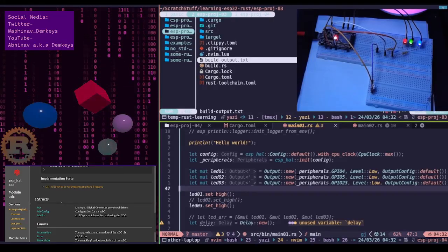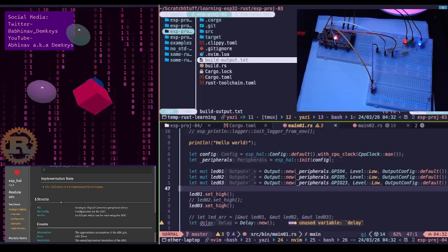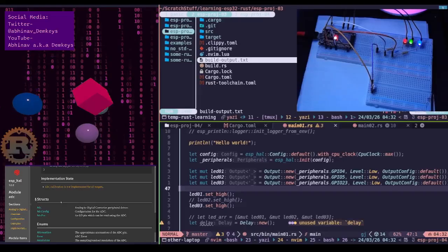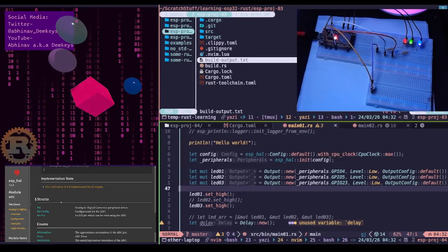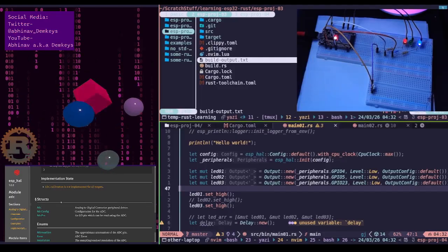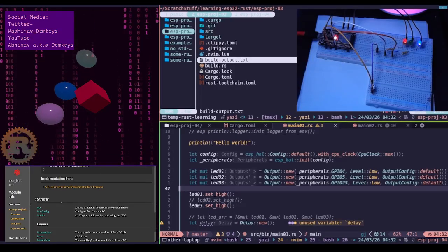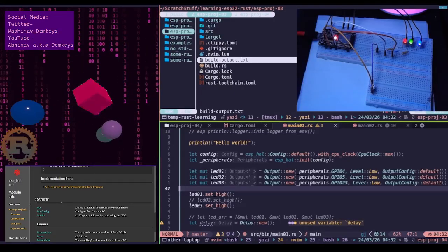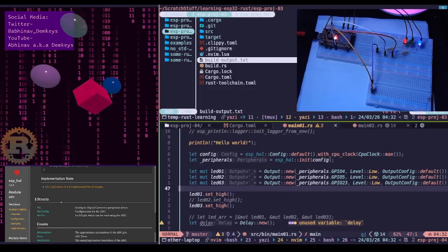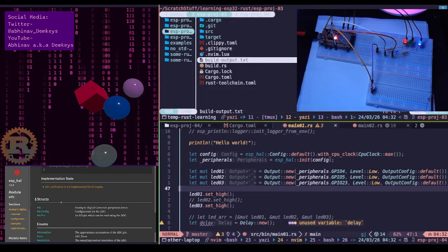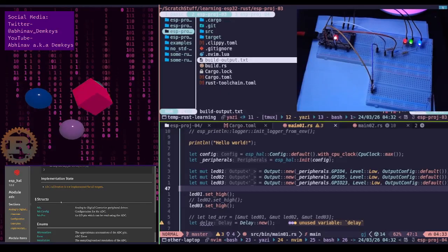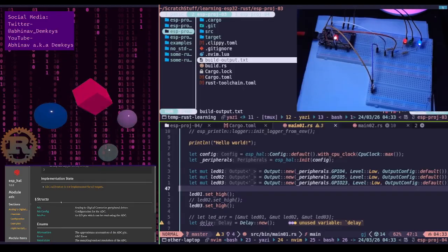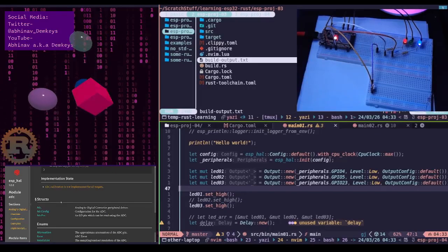The middle point, which is the quote unquote tap or faucet, if you stick a multimeter probe here, you will see 1.65 volts. The voltage has divided based on the ratio between the two resistors. The second resistor, which is R2, the remaining 1.65 volts is used up pushing through this last stretch to reach ground.